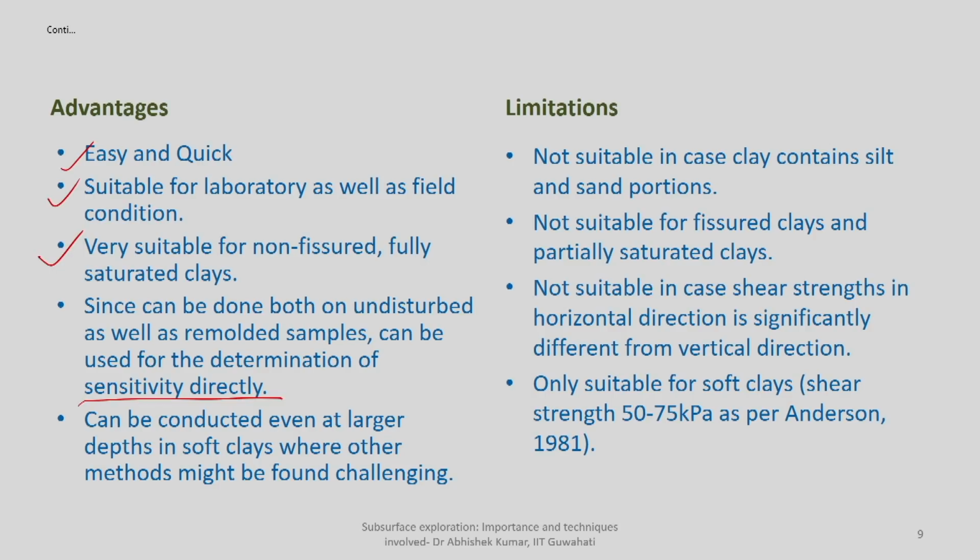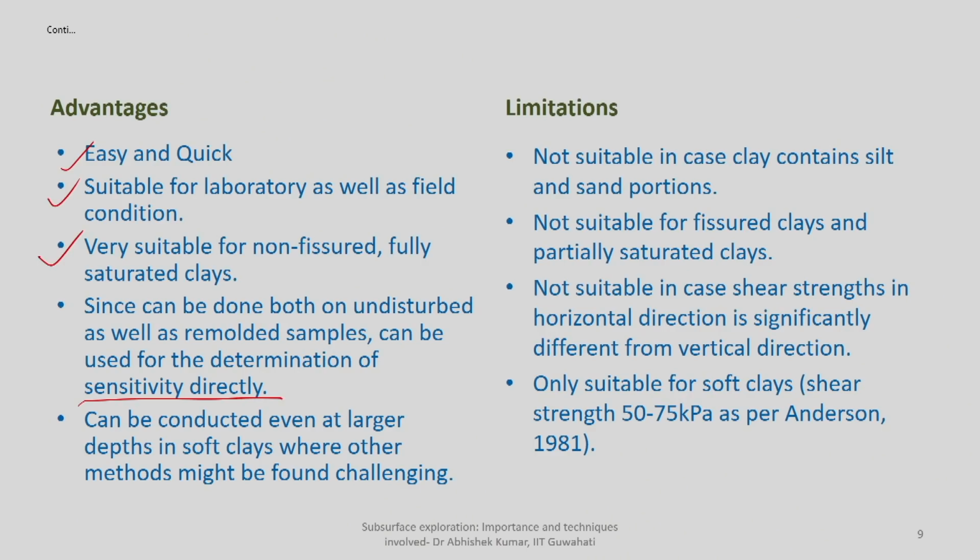Then a remolded soil sample you are able to create at the site of interest, or maybe once the soil has undergone some kind of failure at the site itself, you again do a vane shear test, that will give you how much in situ shear strength is left in the soil which has already undergone some kind of disturbance. So, that is how you can get an idea about the sensitivity, either as a combination of laboratory and field investigation or from field investigation alone.